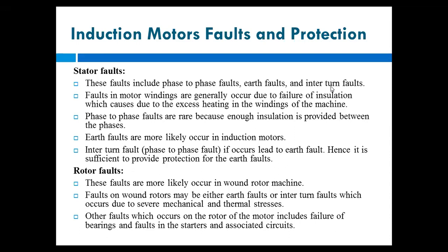Okay, then other faults which occur on the rotor of the motor include failure of bearings and faults in the starters and associated circuits. Okay, so failure of bearings may be in any type of motor, then faults in starters. So different types of starters we are using: star delta, DOL starter. Okay, so different starters we are using for three-phase induction motors.